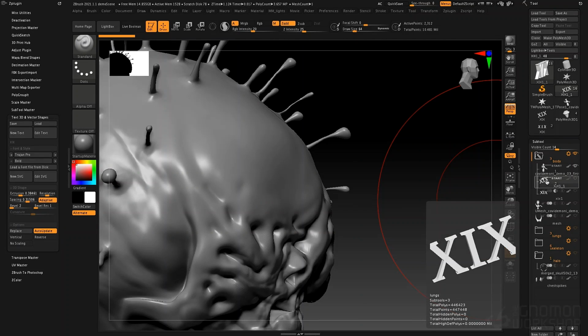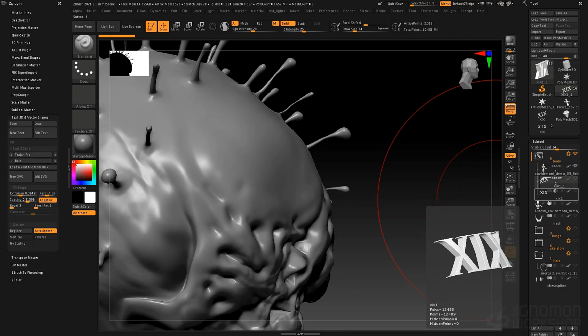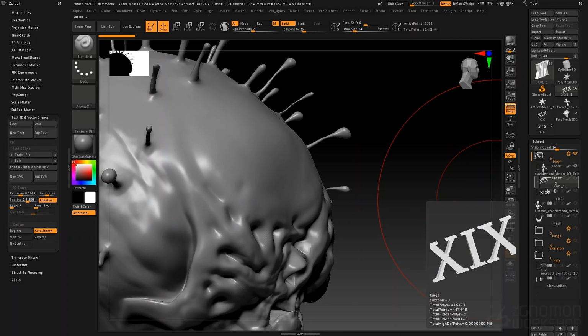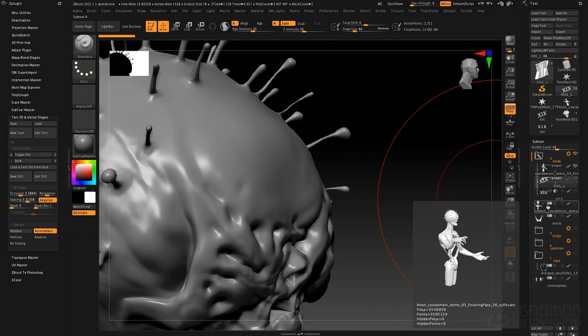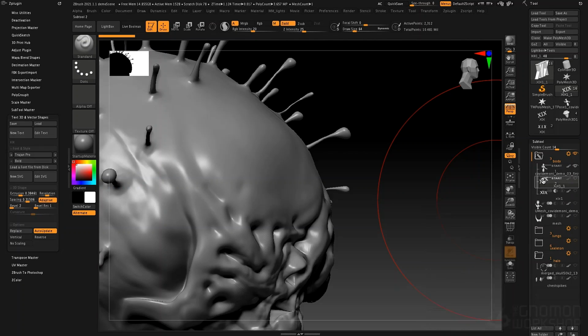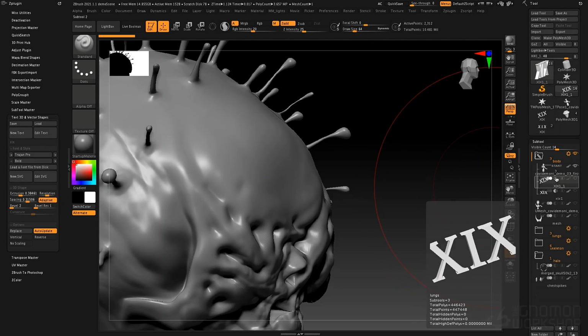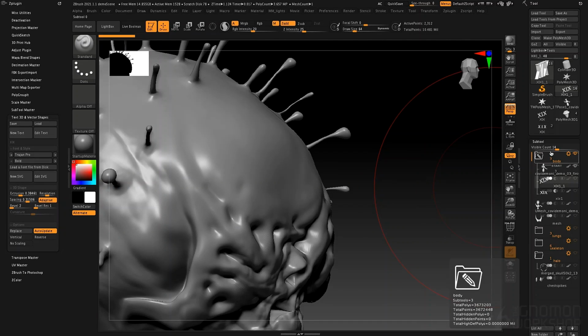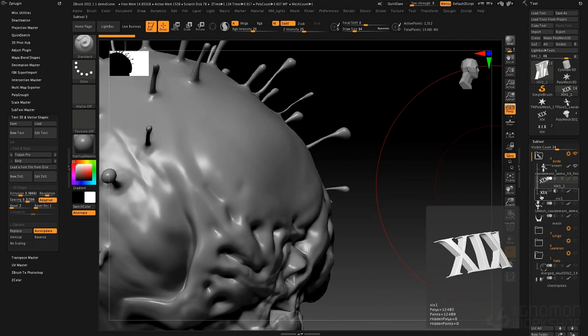In this case, if I have a start group here, it says there's two objects in it. That's the two things beneath it. This and this are in this start group. So that means that these two things will influence this if we have a Boolean set. But we'll turn that off. If you see that, you can just click on it and it goes away. And we're going to use the Boolean options for the folder to actually Boolean this shape.